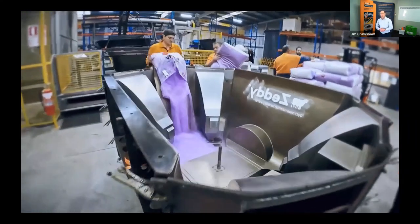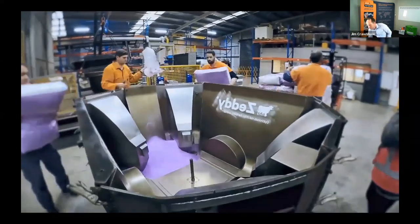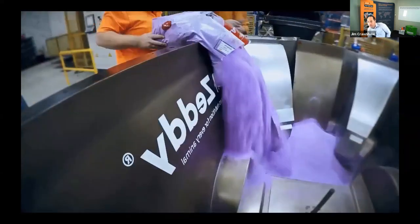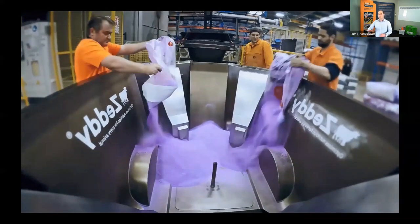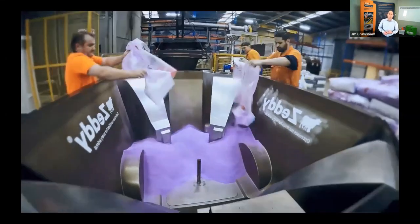So we're loading the material in here, and what you might notice, and I'll just pause it for a second, if I can. I'll wait till I get to a better side. You'll notice on the graphic on the right-hand side, there's a lot of white smeary stuff. What we did is we applied surface enhancer over that graphic. Now that's something that we'd recommend if there's large amounts of powder and there's potential chance of material erosion. So we thought we'd apply surface enhancer to that side just to see if that would help. And thankfully we didn't have any issues.